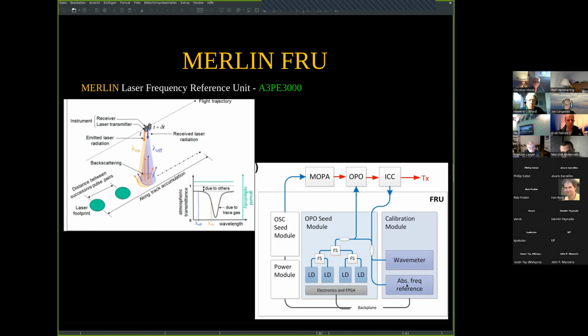A laser beam is sent through this tube every now and then with laser diodes, with receiving photodiodes before the tube and after the tube. So the absorption of the tube can be measured, and in that respect it is very easy to find exactly this region on this frequency.